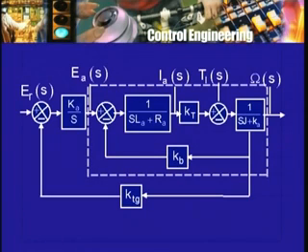If you remember, now if I am only looking at this part of the signal flow graph or block diagram, I have EA as one input, TL as another input, there is a loop, so I have to look at the loop gain. There is only one loop. I look at the loop gain, I calculate the delta corresponding to the loop gain, and then I am ready to write down the expression for the two transfer functions from EA to omega S and from TL to omega S. We have done this already, so I will just ask you to quickly go over it.